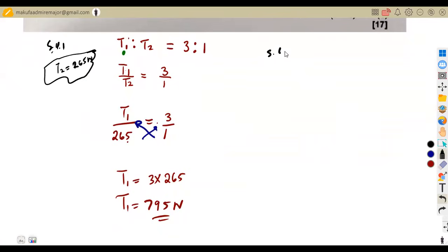All right, velocity is equal to pi dn. But what you need to know is, if we are given revs per minute, we can consider this as a capital letter N. What we want to understand from this formula is that it is taken from either of the diameters. If you are given D2 and D1 and N2, you can choose the ones that you are going to play with. But in this case, which diameter and which rotational frequency are we given?